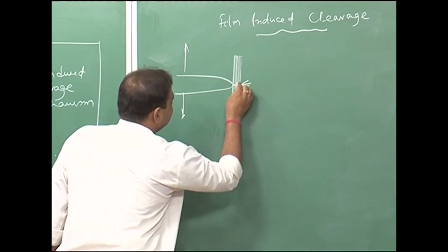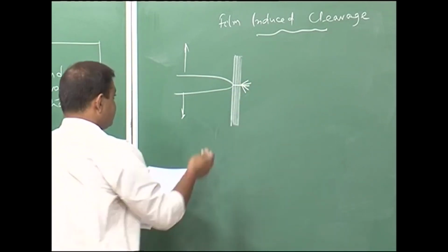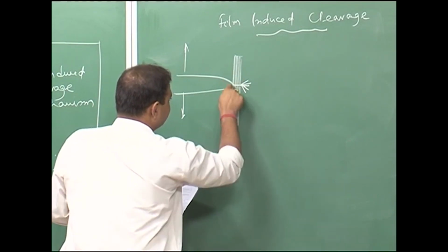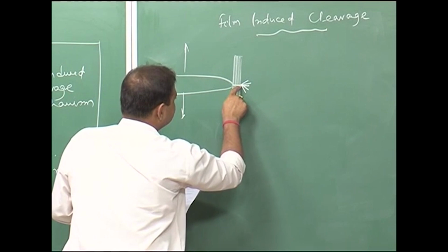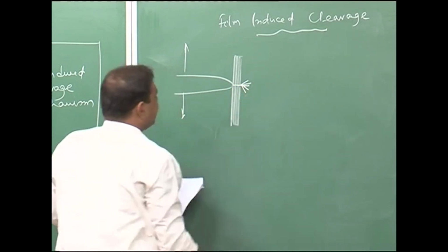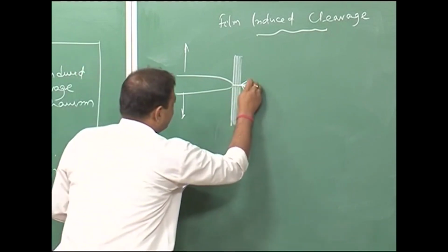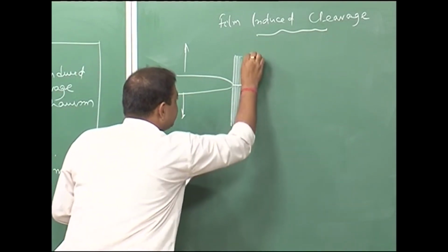So, the fracture is happening in the film, and because of the sharp nature of the film, it can also get into the adjacent volume of the metal, and then the brittle crack propagates a little bit in the metal, and here it stopped again.